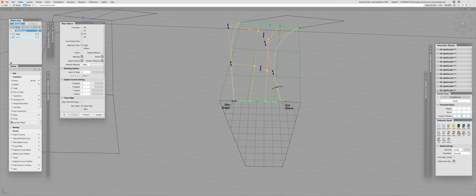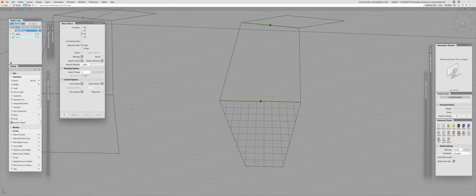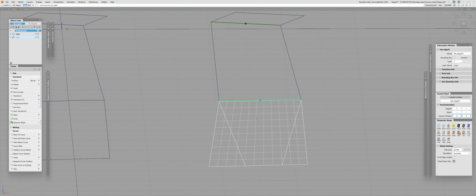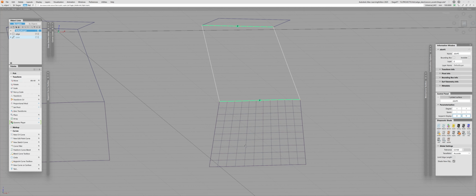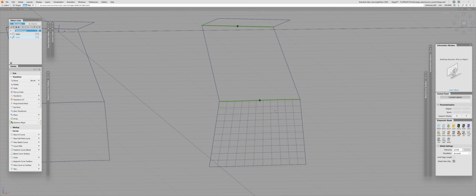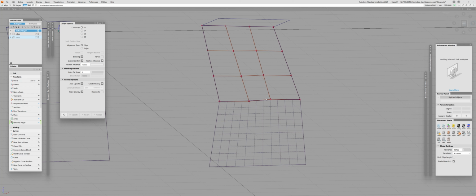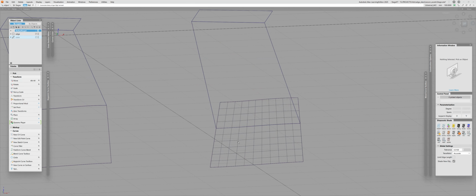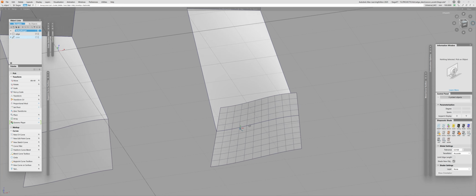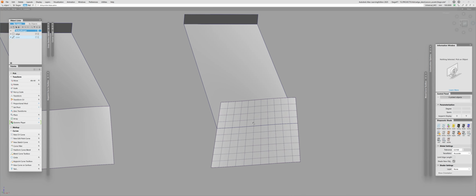This is undesired behavior. If I put that back to the original ones, now it works as it's supposed to, right? But this is not the only problem. If I revert that and imagine that I just delete these curves and surfaces, and I try to align to this surface somewhere to the isoparm. Let me quickly do that. Like this. Let me use the blending. Actually, I delete the history like this. So imagine that the surface was like that, and now I need to align these with edge align.